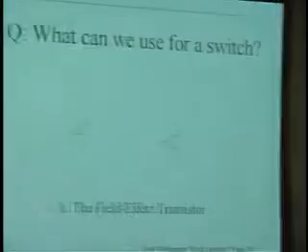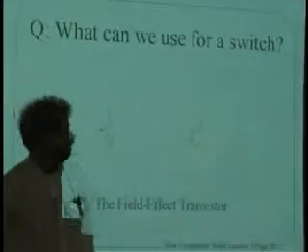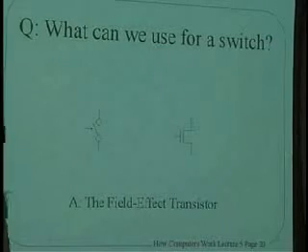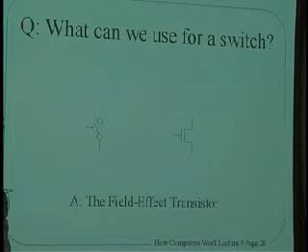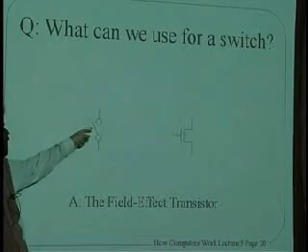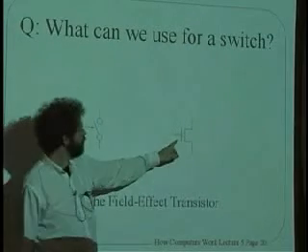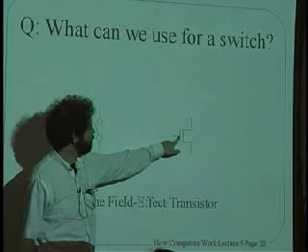And what is the switch? Here's the answer to your first question, that excellent question you asked. What is a switch? The switch is this thing called a field effect transistor. Okay, and we're going to talk a little bit about how this works, but we won't get too deep. This device on the left, which I've drawn as a switch controlled by a wire that allows the switch to turn on and off, is in fact this device right over here, which is a gate. That's what this thing is called here.